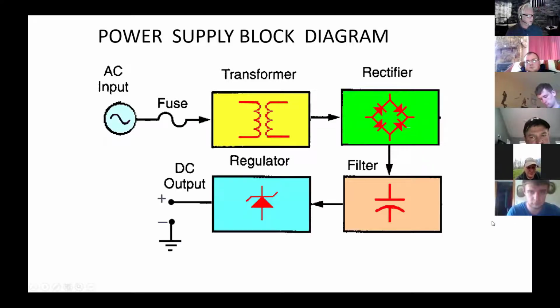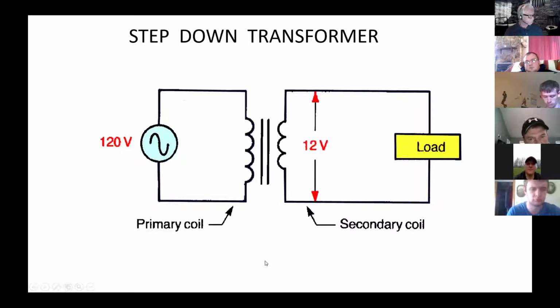A regulator is usually a semiconductor device that maintains a constant voltage. A lot of times your house current can vary. If you could measure it one day and read 105 volts, you might read it another day and it says 125. And that can happen at any instant. Any rise and fall in the AC is also going to be introduced to the primary windings, passed to the secondary. So to keep that fluctuation from occurring on the output, this puts a ceiling on your voltage to keep it constant.